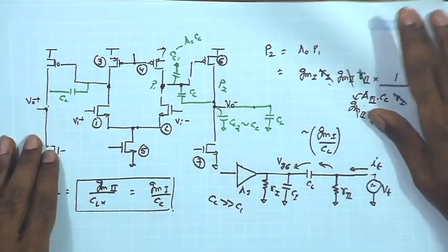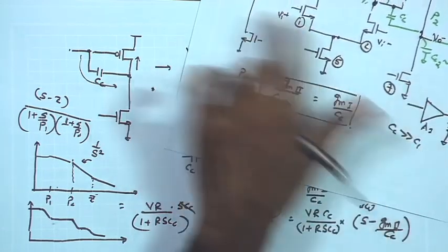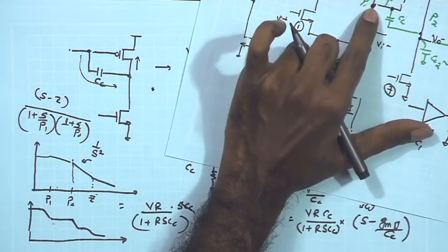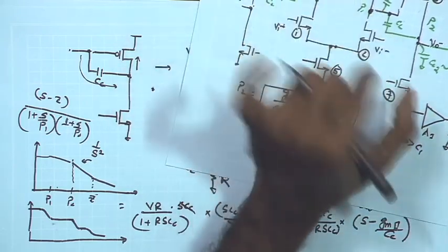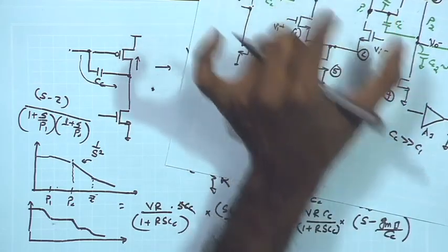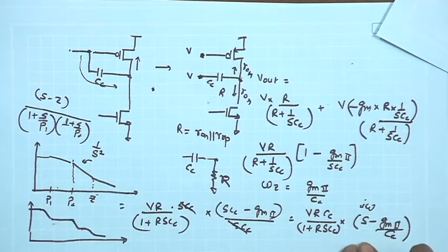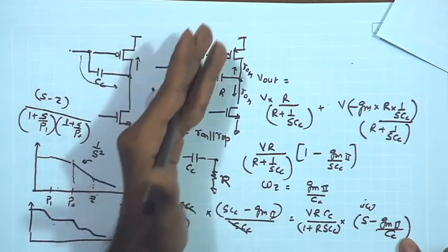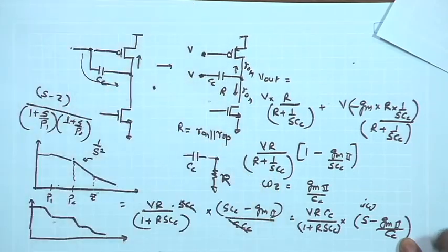And there again you can find out the exact expression of 0 coming in the numerator along with the terms in the denominator, factor them out and get the expression for the exact poles, and there you can take approximation and arrive at a more exact value of these poles. So, here while considering the effect of 0, just to show what the mechanism of origination of the zeros is, we are using this model while ignoring its connection with the previous stage and the impedances provided by the previous stage.